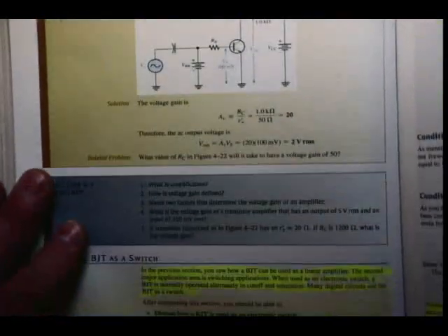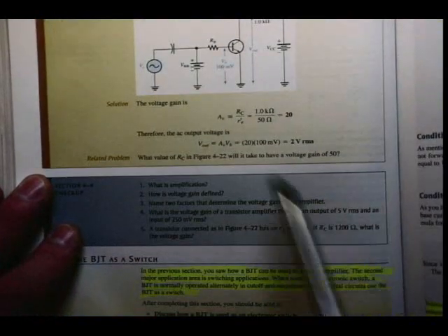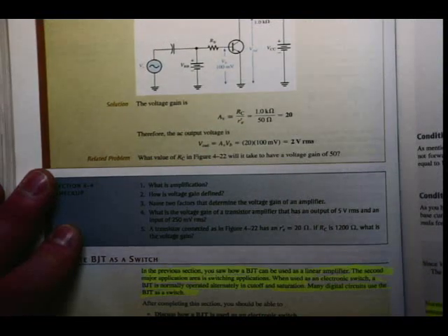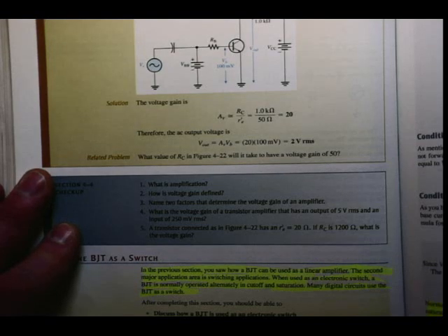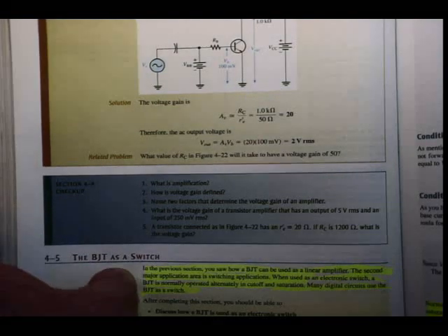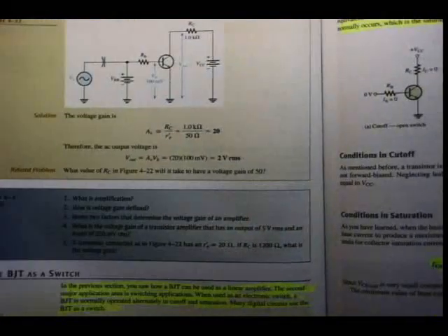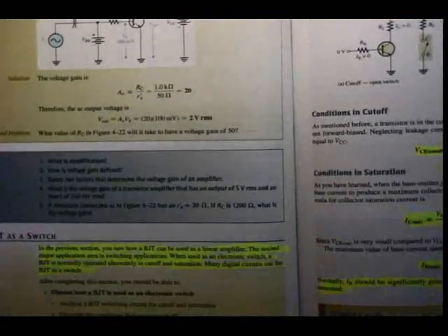Okay, the example there is just an example to show me how to determine the voltage gain. Voltage gain there, RC divided by r'e. RC in this case 1 kilo ohm divided by 50 ohms, and I have a voltage gain for this specific amplifier of 20. So the output signal is 20 times larger than the input signal. But it isn't always this simple. In later lessons we will see how to do this more accurately.